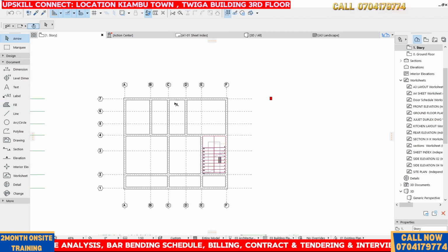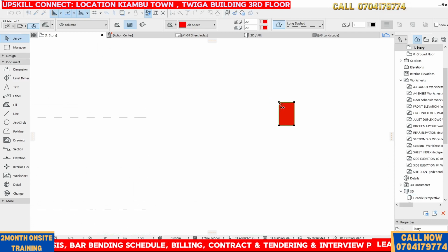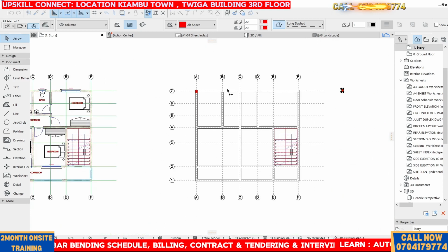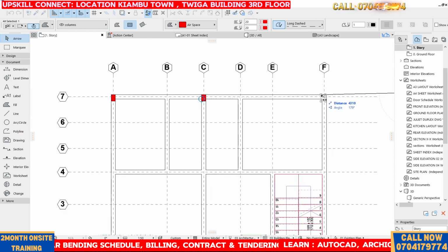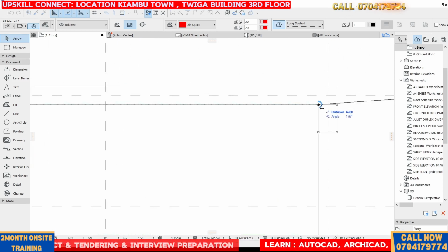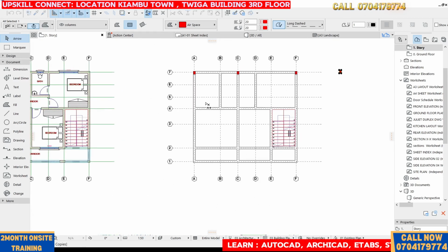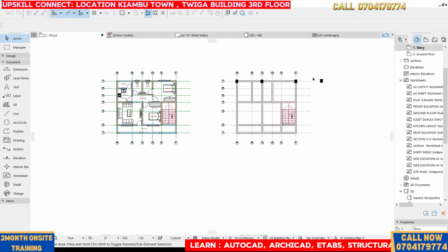Then I'm going to place the columns. Now let's do this. So move, drag a copy or multiple copies. So guys, I want now to place my columns. So I can place a column there, let's place here, guys. This will depend on the experience that you have. But there are thumb rules, for example, distance, the span, and all that, and also the architectural plan.